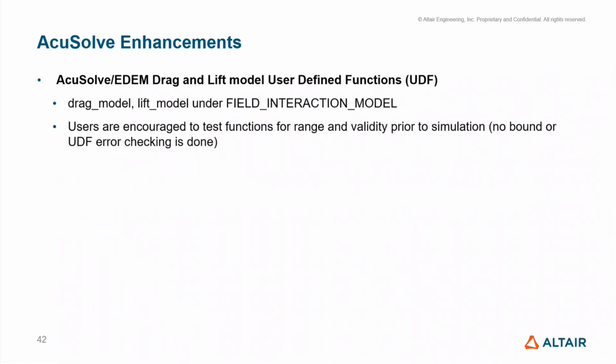Another enhancement is the ability for users to define their own lift and drag models for AcuSolve EDEM coupling through user-defined functions. This has been added to the lift model and the drag model definitions under the field interaction model command. Users are encouraged to test their functions for range and validity prior to running them in a simulation, because AcuSolve doesn't perform any bound or error checking other than syntax.